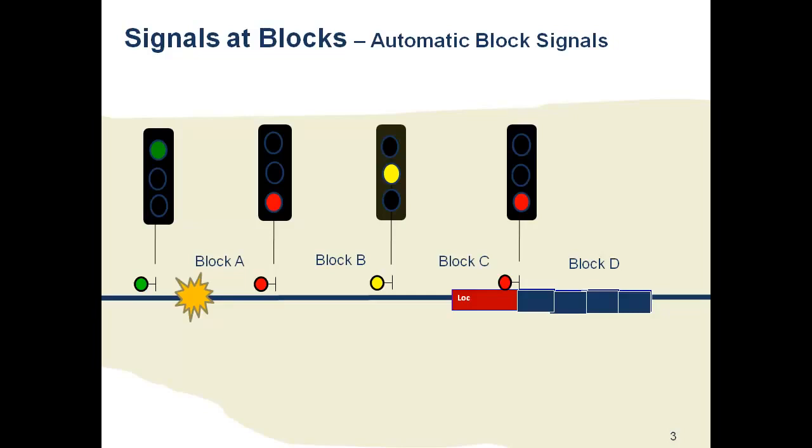All right, so I have a question. The train engineer sees a block signal ahead that is normally green but is now yellow, like in the diagram shown. Does the train engineer slow down and just wait? When a train engineer sees a yellow, he or she would typically apply the brakes. If the yellow is unanticipated, then they would call the dispatcher to ask about the situation. The dispatcher could respond that there is no train ahead and to slow down and crawl forward to see what is causing the signal to change. Or he could say you are following train XYZ and wait until the signal changes.